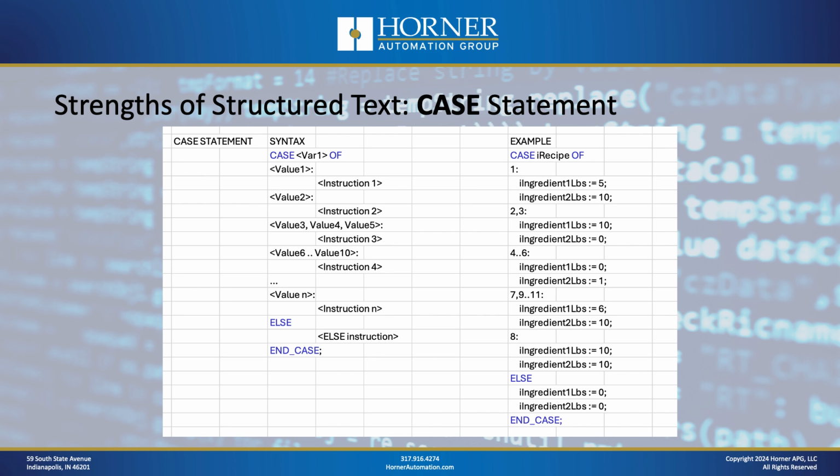So instead of, let's say I had 100 conditions in the case statement. Well, if I did this with ifs, it'd be 100 ifs. And even if I came across one of the ifs that was true, unless I had a jump that passed over the rest of the ifs, I'm still going to solve all the rest of the ifs. So scan time wise, this is the most efficient way to do a lot of comparisons against the same variable. Awesome. Yeah, it's terrific. I agree. It could be really, really handy.